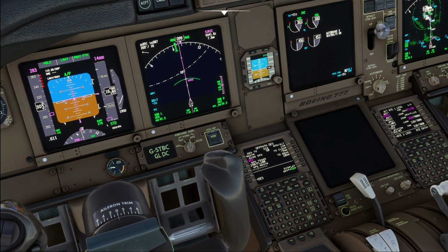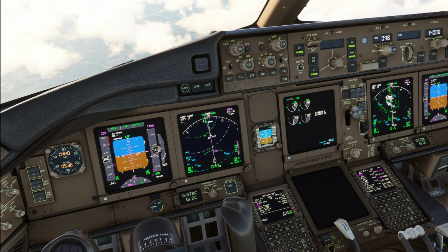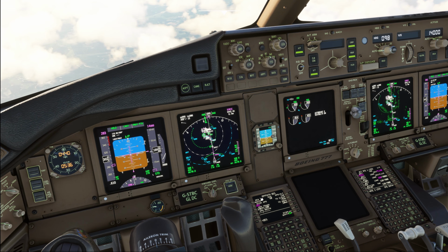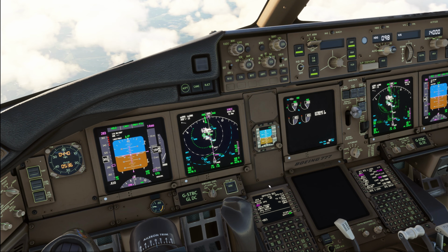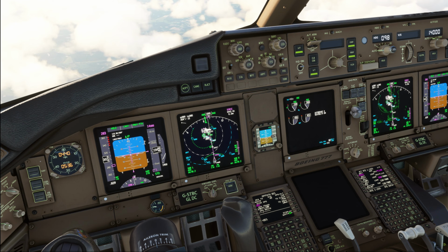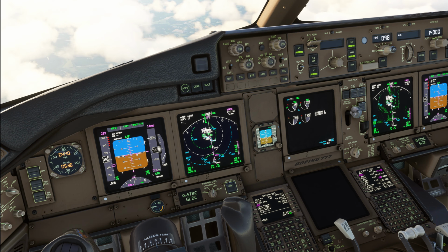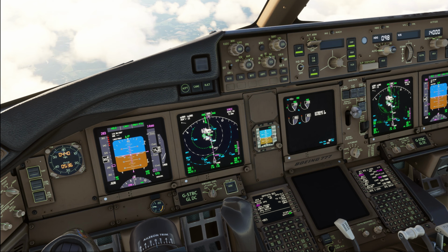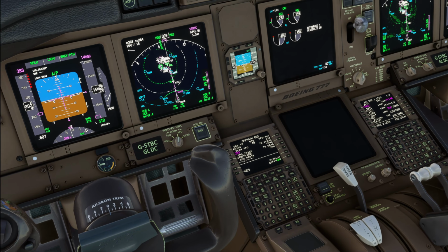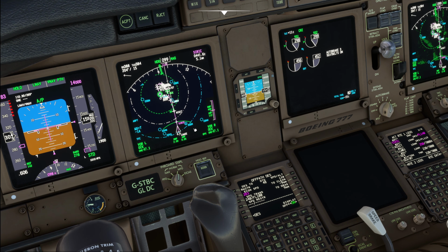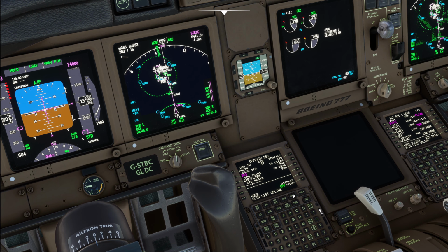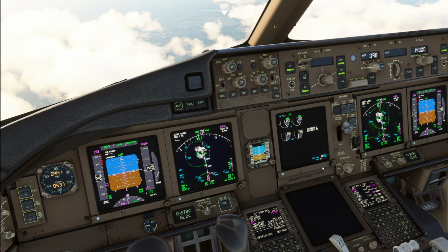Can remove that again, and now the runway is re-entered. You can enter any waypoint and altitude combination on the off-path descent. So this provides a really good feature for you to control your descent and cross-check your descent distances. Of course, we got to be aware when we can use it. So right now, since we still have to fly around the airport and come back, there is not really any sense in using this. So we can switch the display off again. And that's the off-path descent feature in the Boeing 777. Really cool feature if you know how to use it.